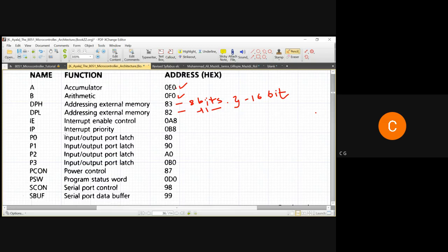And then there is an interrupt priority, right? This priority can be set by the value of the various interrupts available on the microcontroller. Otherwise, you will have to make sure by using some different ICs as well whom to give priority.